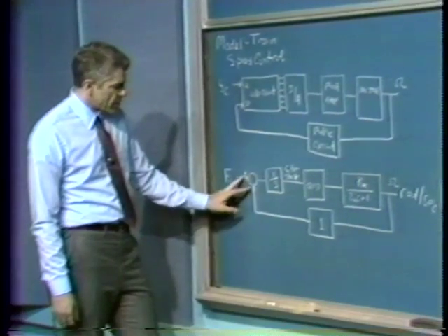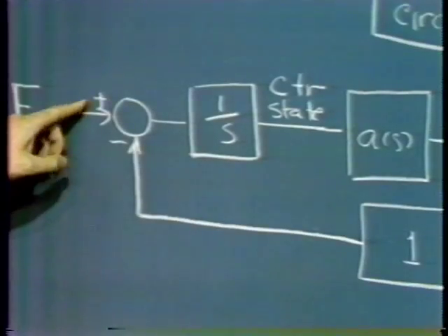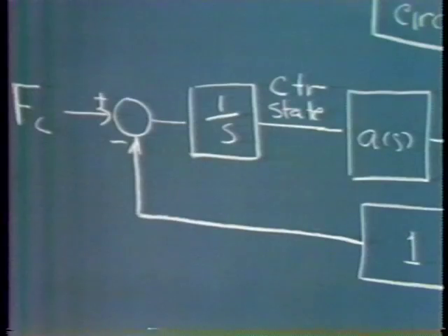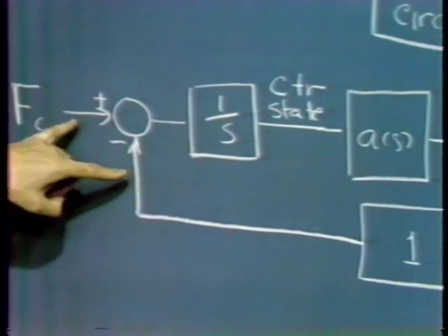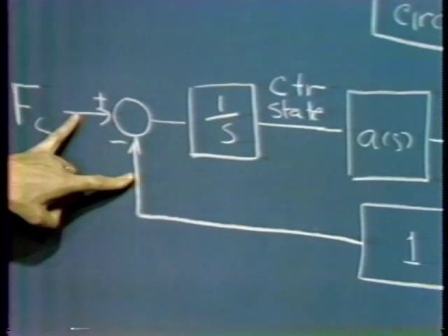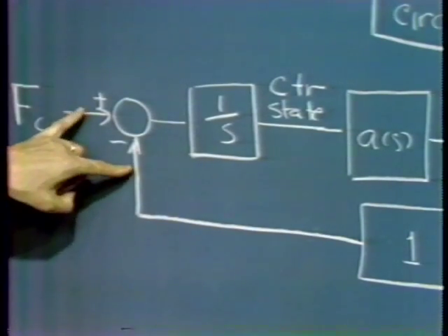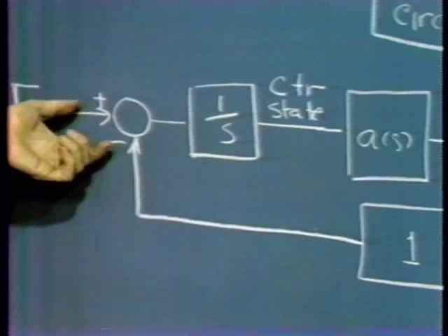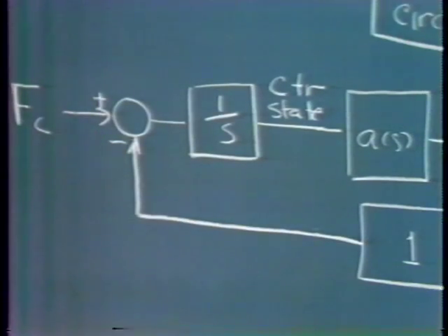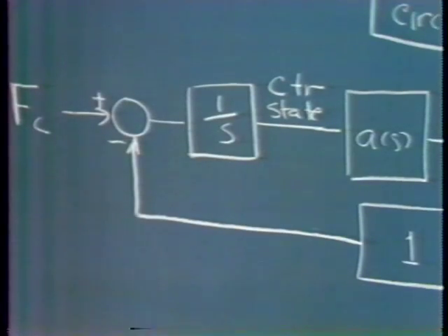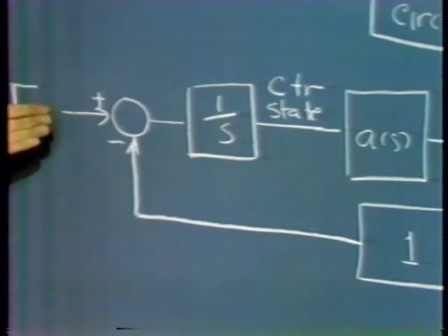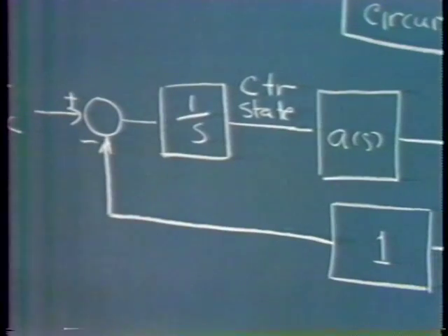Those are the down pulses. The up-down counter subtracts down pulses from up pulses, and the net count in the counter is the integral of the frequency difference between these two signals. Of course, as we have in a normal phase lock loop, the phase detector, in this case the up-down counter, is measuring the net slippage in phase, if you will.